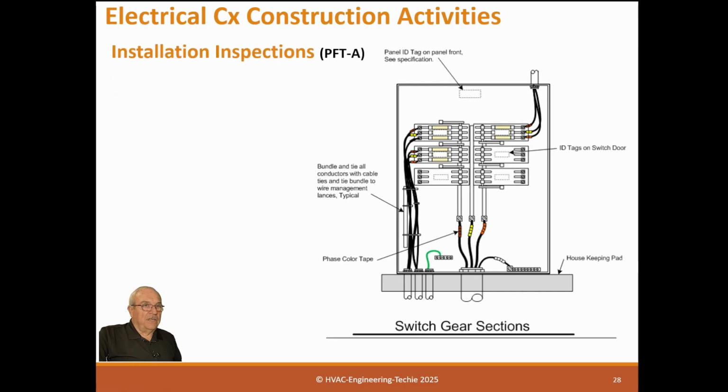All right, so then in a transformer, same thing. We're going to look at transformer wire management. Now, why I'm saying wire management, some panels are different. Some transformers will not allow wiring above these transformer coils. See, this one shows wiring entering and going out the top, and some transformers are rated that way, but some are not. So this must come down and go out here below.